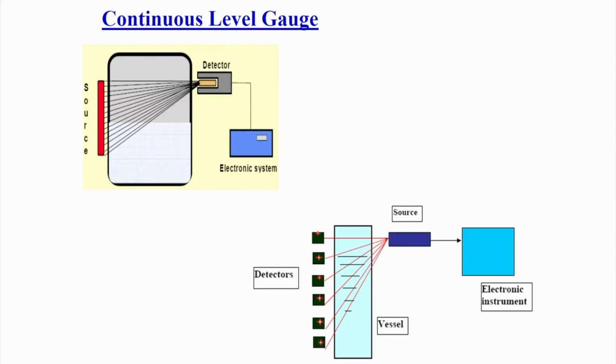Similarly, these techniques are also used to do measurement. Say I have a tank and I want to measure the liquid level inside, and the level is continuously changing. So, there are two ways. You put a glass tube inside and someone goes and always reads that reading, or you can use a source, okay, which will have a fan beam kind of structure, and there will be a detector, okay, which will be detecting it.